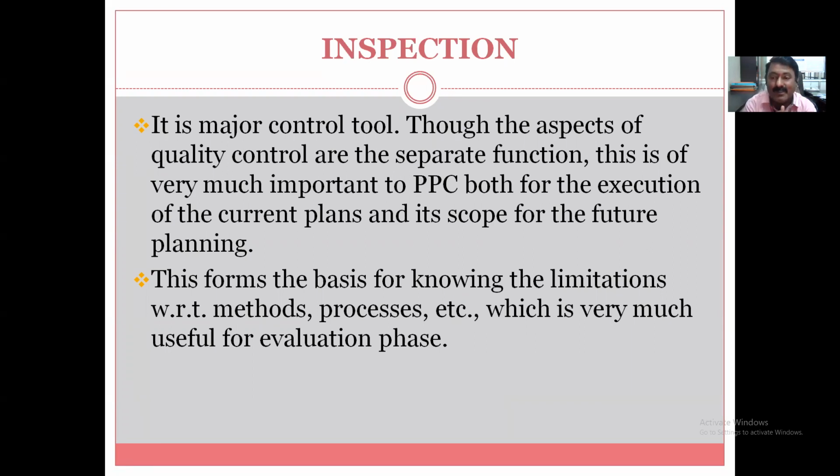This is for surface finish. Then this is for the stringent tolerances, depending upon which machine you are choosing. If you have a very high surface finish requirement, you have to use grinding operation, then lapping, honing operations; these are the different operations you can go for.